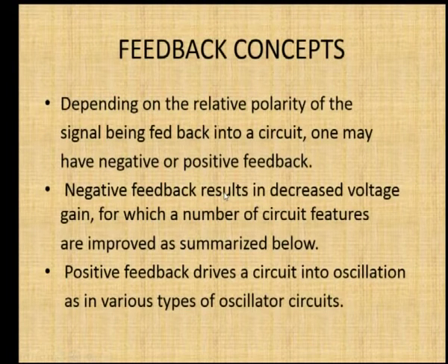In the concept of the feedback, if you give part of the output signal as feedback to the input signal, you can give it as a negative feedback or you can give it as a positive feedback. If it is a negative feedback, we already saw that it is an amplifier. If it is a positive feedback, it is an oscillator. If negative feedback is given, what are all the circuit improvements we are going to see now.